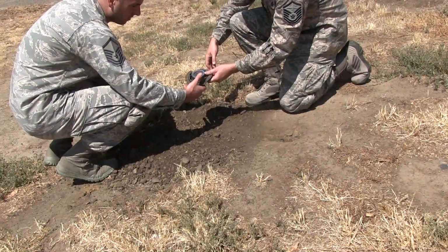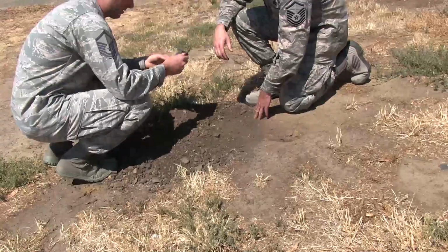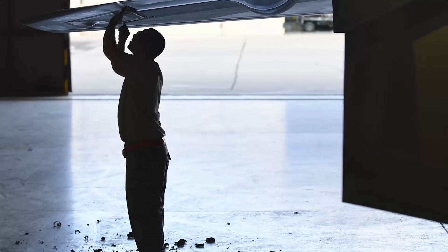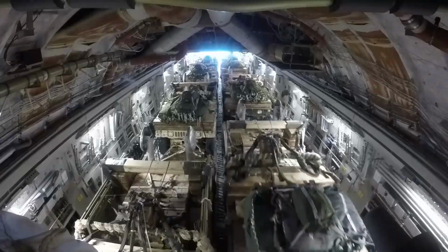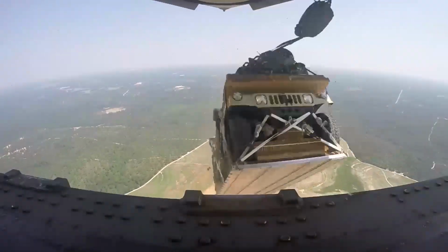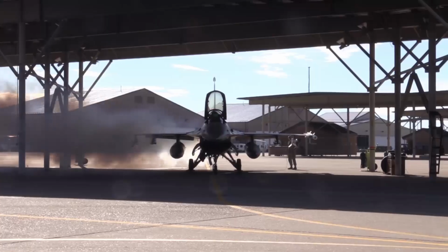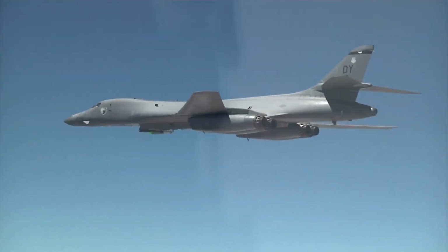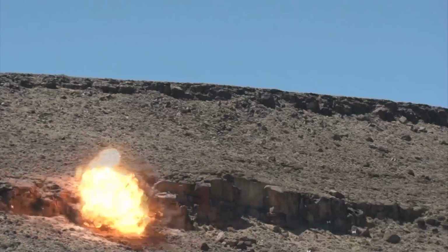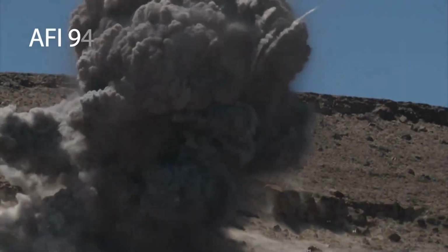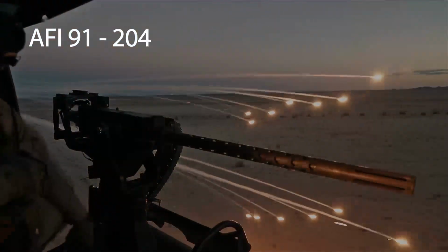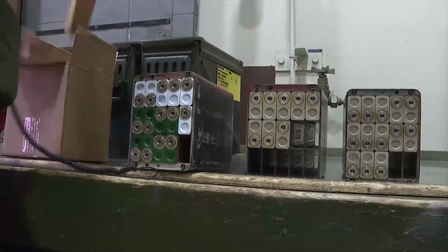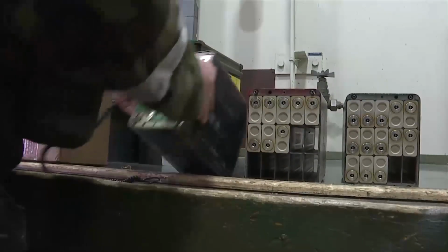A dropped object is defined as any aircraft part, component, surface, or LO coating exceeding 8 inches in any dimension, or other item lost during aircrew operations, unless intentionally jettisoned, from engine start to engine shutdown. Inadvertently released munitions are not considered dropped objects and will be reported in accordance with AFI 91-204. Note, missing chaff, flare, and decoy end caps are not reportable dropped objects.